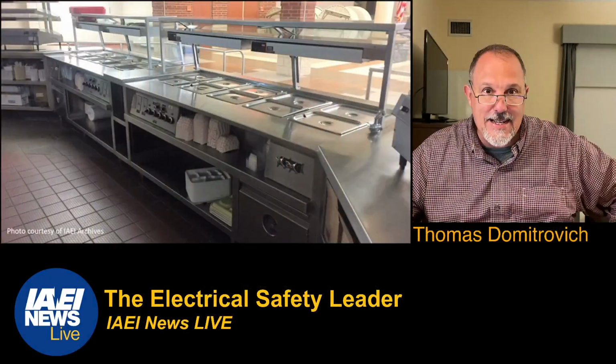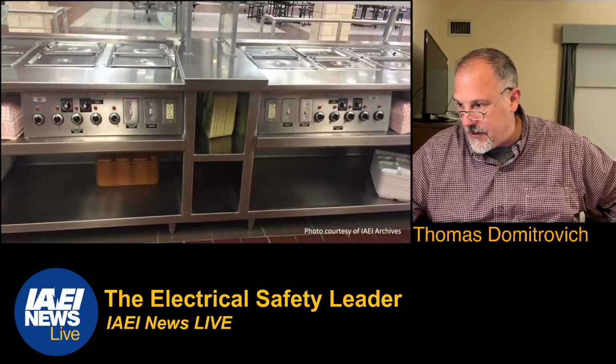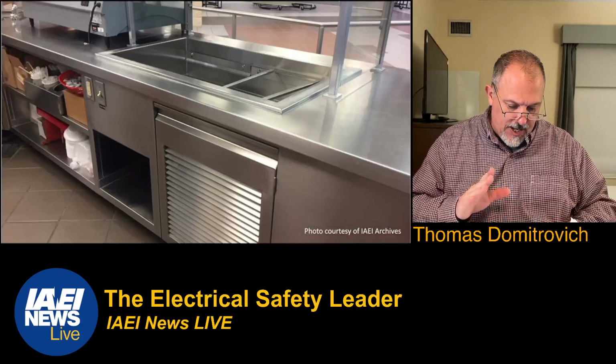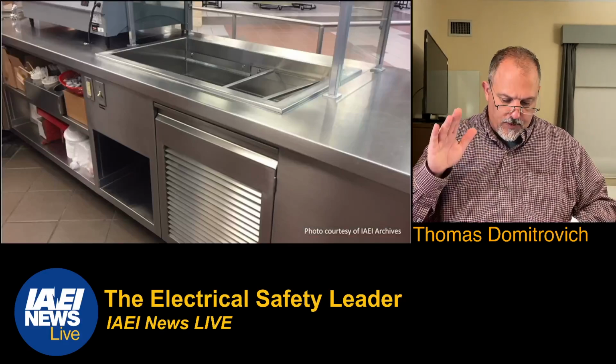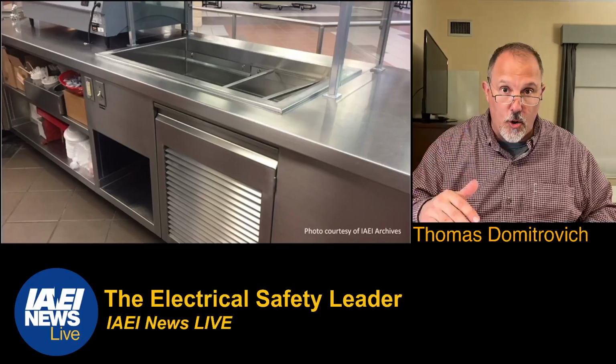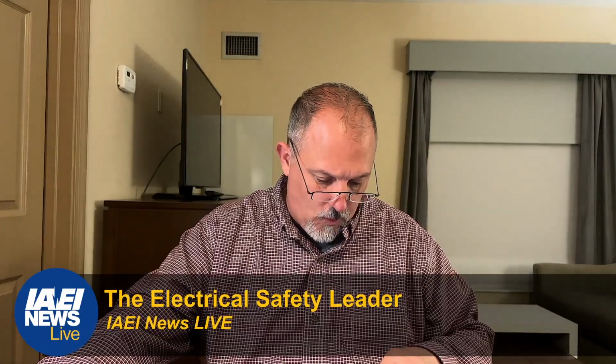The other thing we did was we added buffet serving areas. We added these areas that are now required for GFCI protection. We said buffet serving areas with permanent provisions for food serving, beverage serving, or cooking. So they're not a kitchen, okay? So we have those, that's in list item 4.